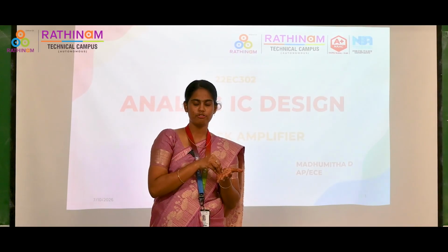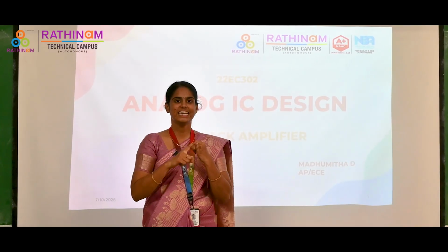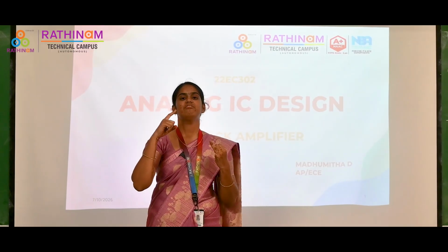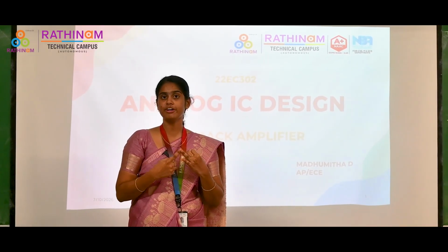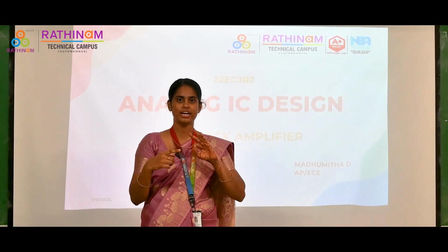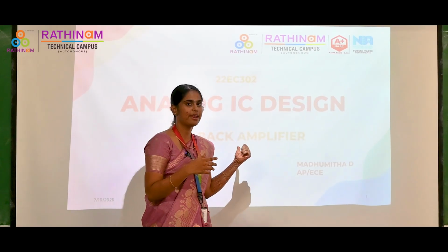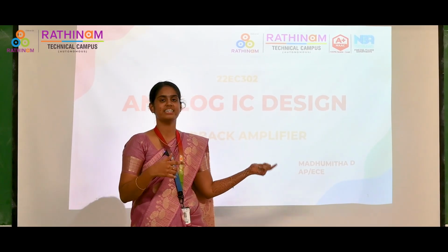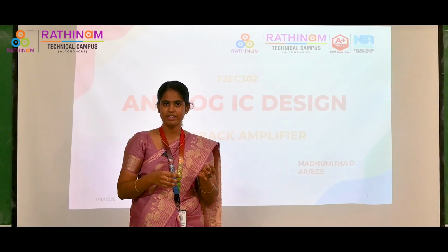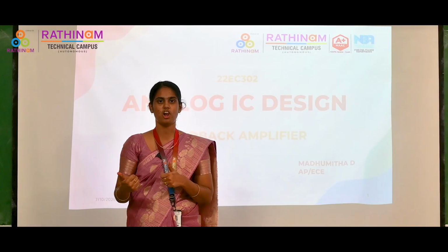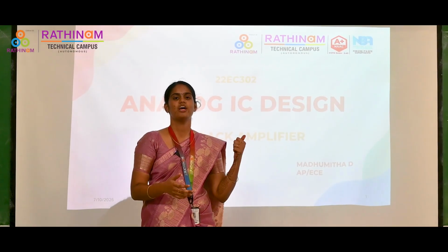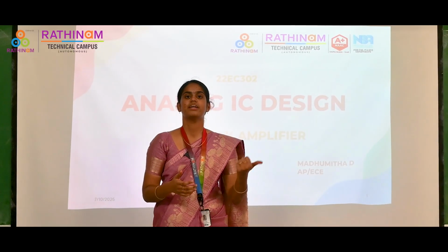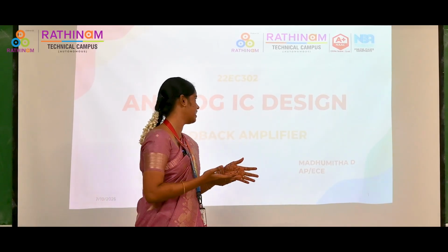In order for a smartphone to understand a human voice, we need a microphone to record the voice, an amplifier to amplify the signal, a filter to reduce the noise, and finally an analog to digital converter to convert it to digital data. All these components are designed based on the concept of analog IC design. That's why analog is the bridge between real world data and digital data.